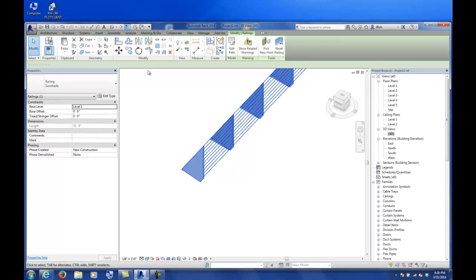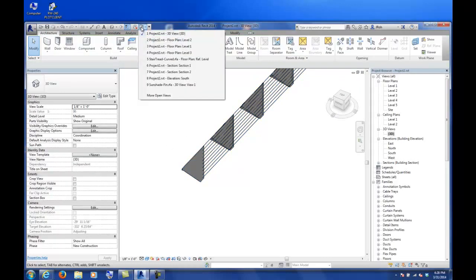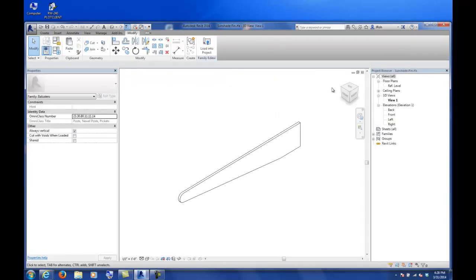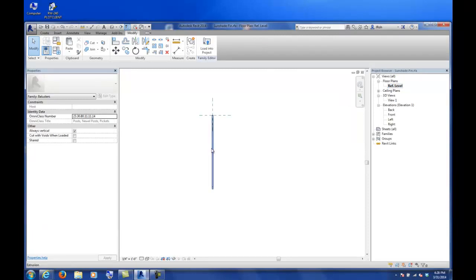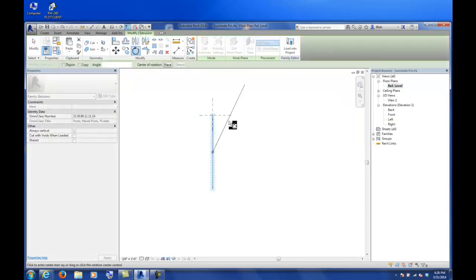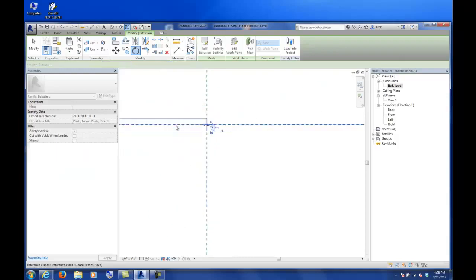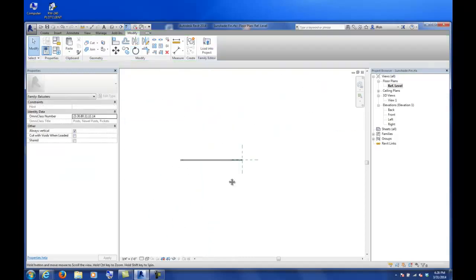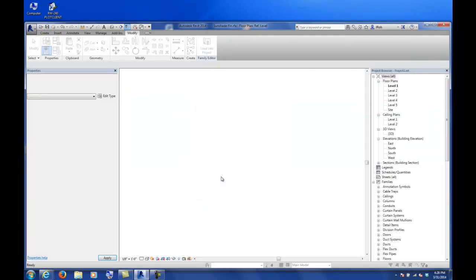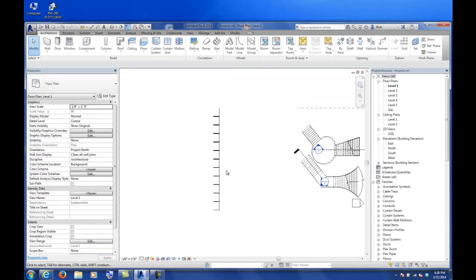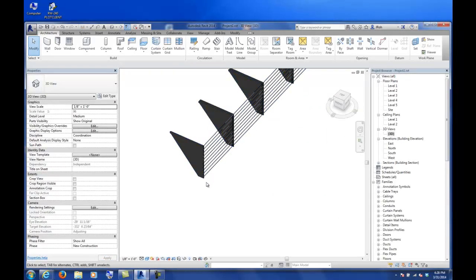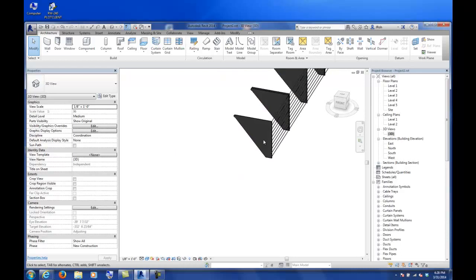So I actually need to go back into this sunshade fin, and I'm going to rotate it by placing the origin point here at the origin. I'm going to rotate it 90 degrees. When you load that back in and hit overwrite, there we go. Your fins should be, and they're going to stretch like this, but we'll fix that in a minute.